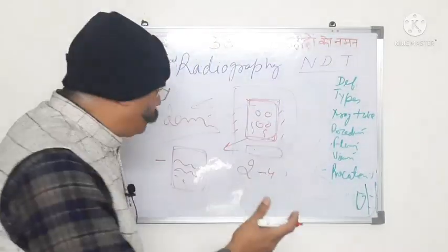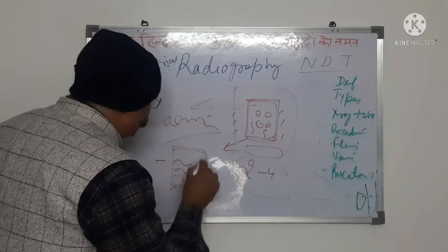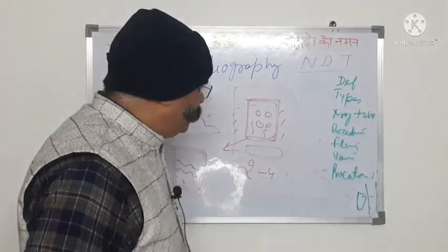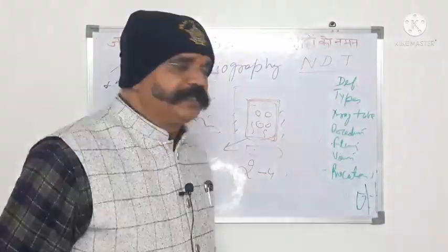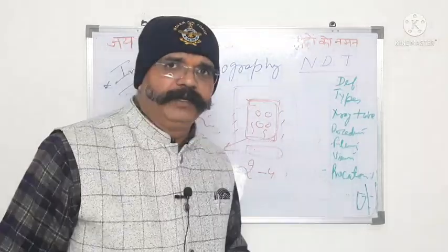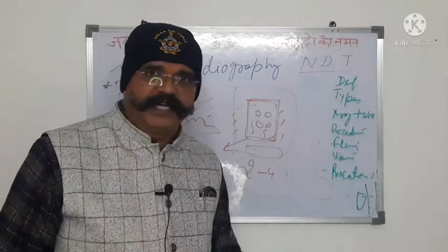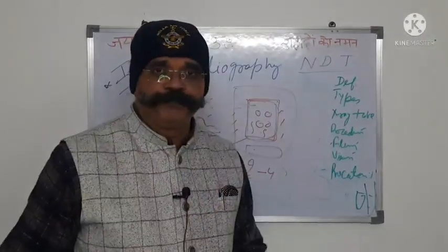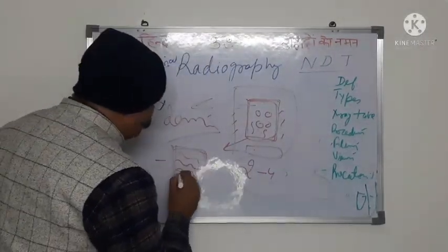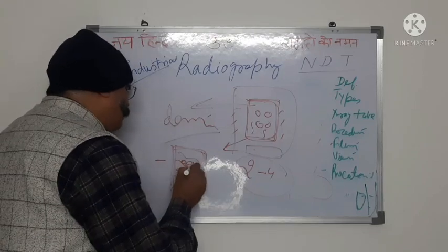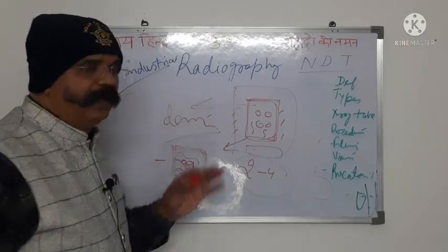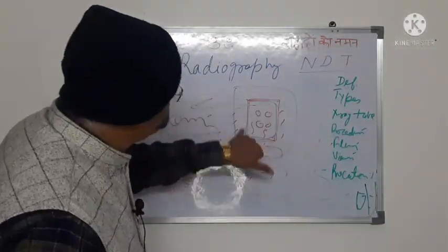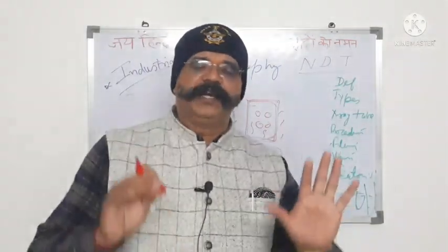And contrary to that, if heavy darkness has been given to this X-ray film, that means much more energy has been given to the X-ray film, either by the X-ray radiation, by sunlight, or by some other radiation. So again, if there is heavy darkness, you will not be able to differentiate between the cracks and all the non-cracks area. So here also the density of the X-ray film has a very important role.